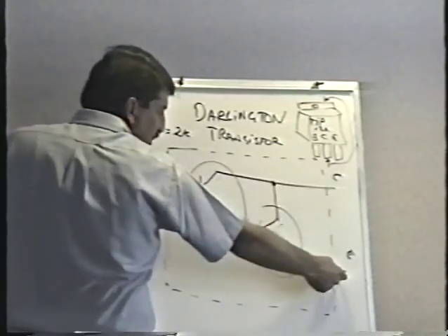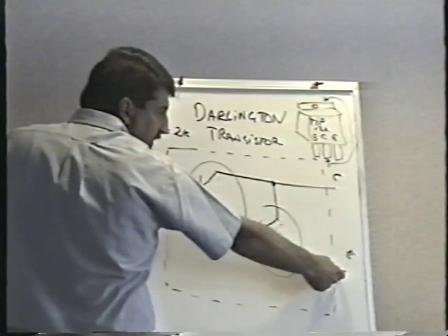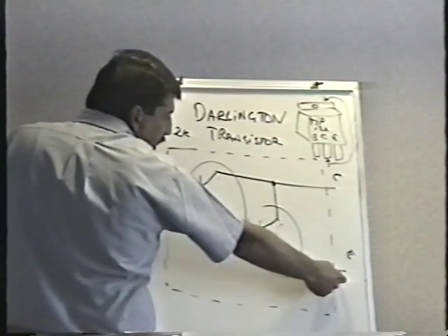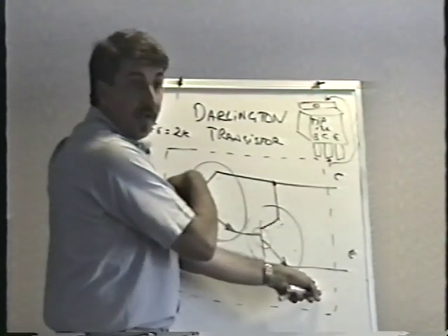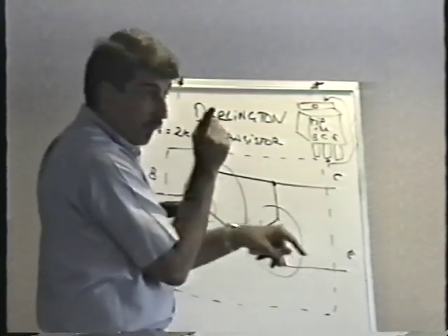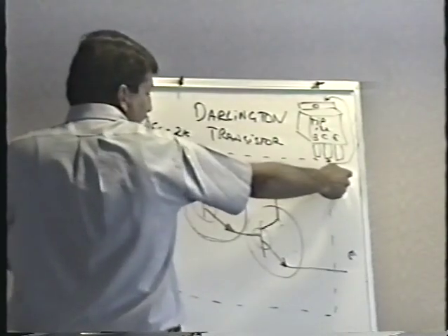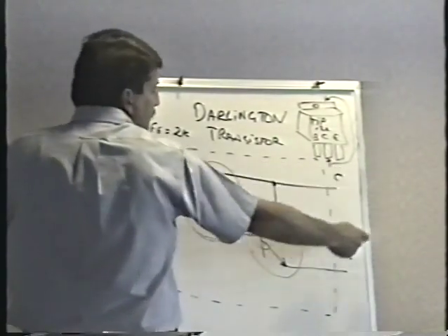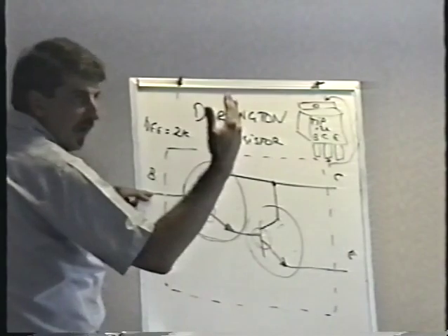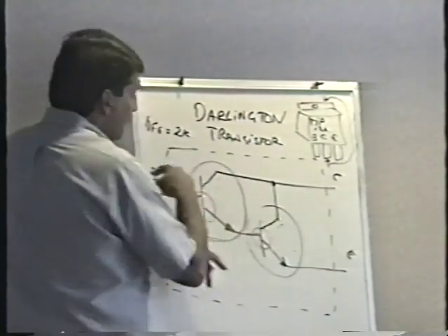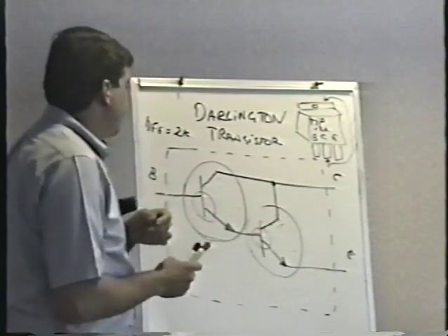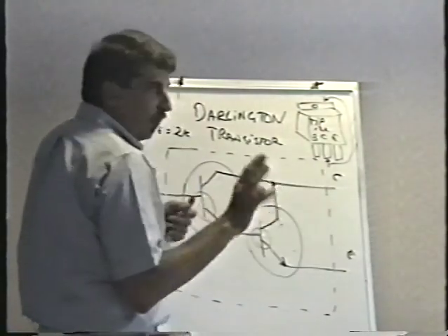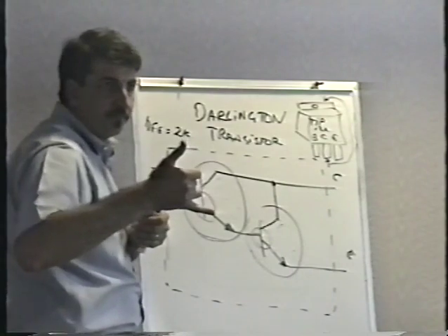When you reverse the leads, though, that's perfectly normal. Open reading, just like before. One more time. Base to collector, normal junction drop. Base to emitter, something somewhat higher. Reverse the leads, open. Now, final check. Remember, between the collector and emitter, in a normal transistor, what do you see?